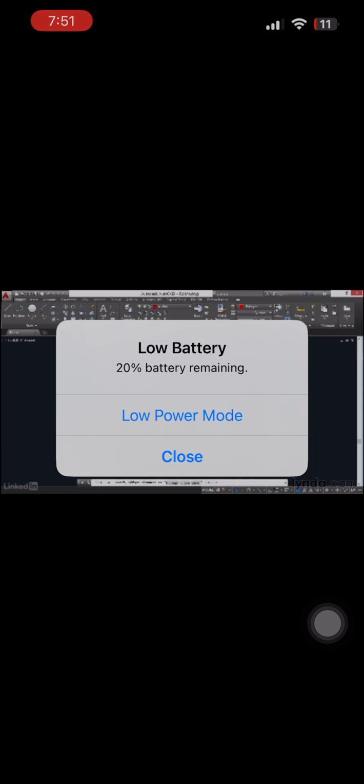Unlike most of the other modification tools, this one does not begin with a Select Objects prompt. Instead, it says Specify Offset Distance. We can type in a value, or click 2 points to have AutoCAD measure something for us. This first time around, let's just click 2 arbitrary points that aren't too far apart to specify some offset distance. Now the command prompt says, Select Object to Offset.